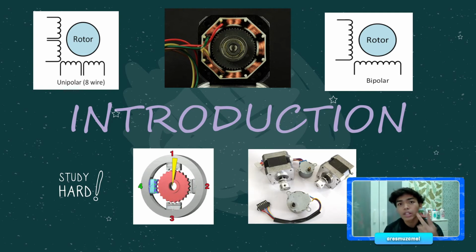The second one is the variable reluctance stepper. It has a plain iron rotor and operates on the principle that minimum reluctance occurs with minimum gap, so the rotor is attracted to the stator magnet poles. The third type is the hybrid synchronous stepper, a combination of both above to maximize power in a small size.